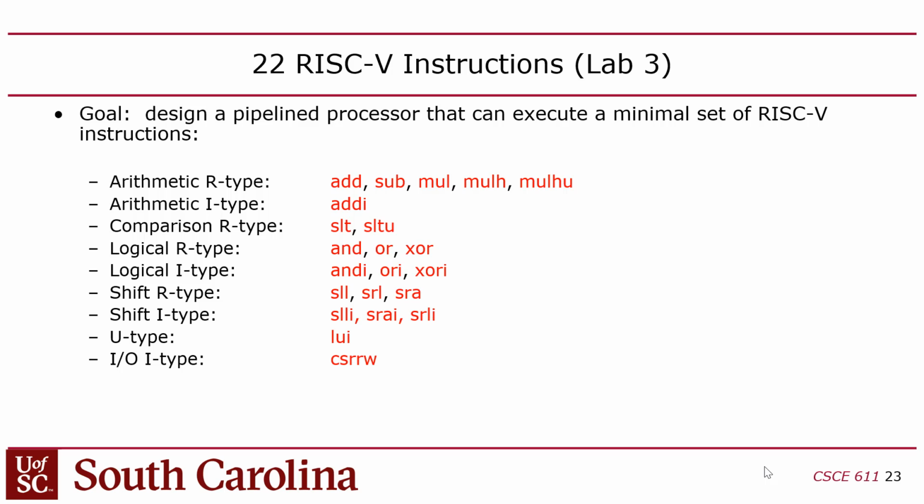I don't remember now. What is it? It maps to like a shift instruction, I think. If you look at the bits, in other words, if you look at the opcode, the function 3 and function 7, if they're all zeros, what instruction is that? I believe it's a shift, right? However, which writes a register, right? But the destination register is also 0. And remember, if you write to register 0, it doesn't actually write to register 0. So a no-op actually will write to a register, right?